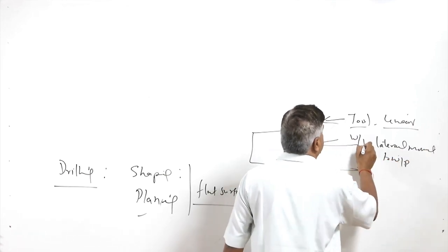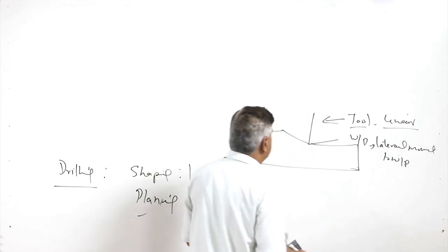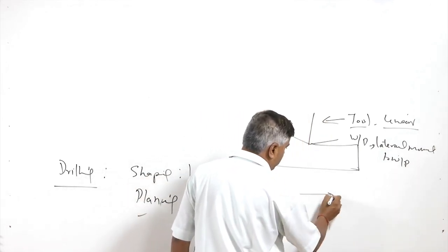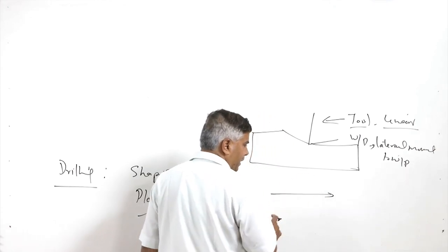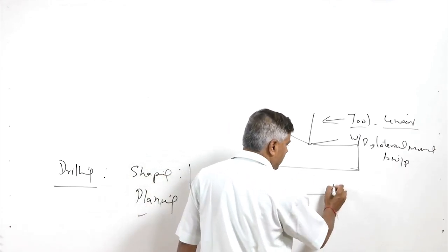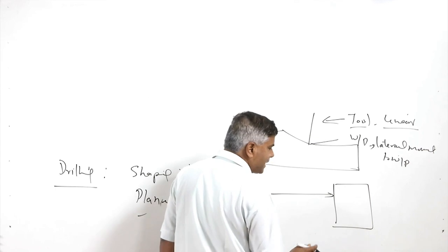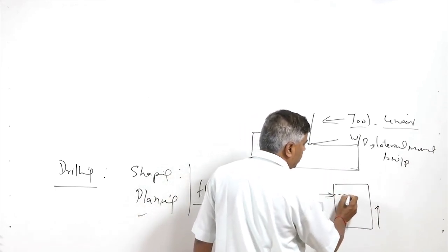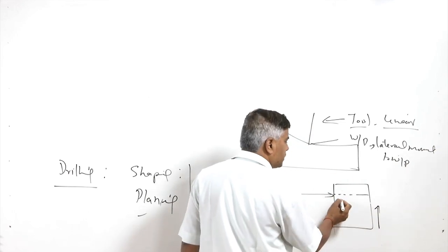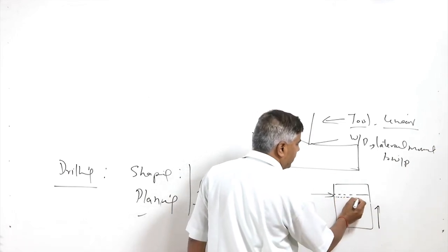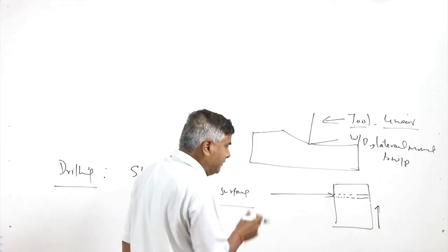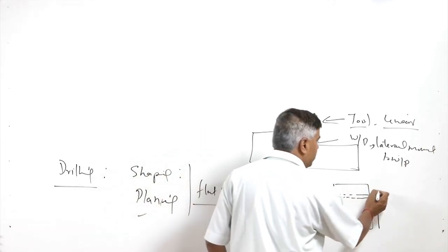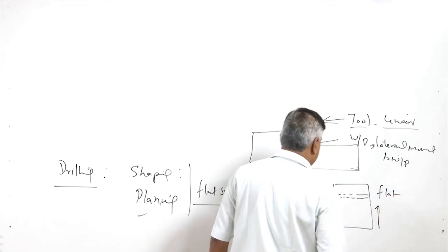The tool is always moved along a particular line for producing the cutting, but in order to cover the entire surface area, the workpiece is moved laterally. So, in one go a cut will be made, then the workpiece will be moved laterally, and then a cut will be made at another location. These combinations result in flat surfaces.